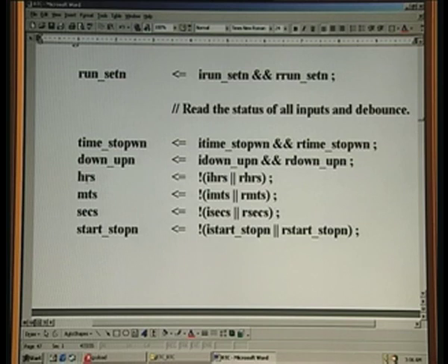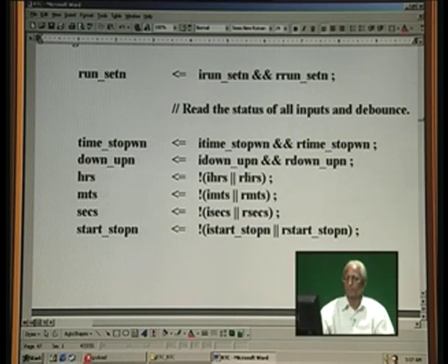If you want this active high, note that we need to OR the present one and the previous value of the push button. So when both are the same, for example both are 0 0, that means it has been pressed 3 milliseconds or more prior to this. That means when you press this push button, it is 0, not 1.